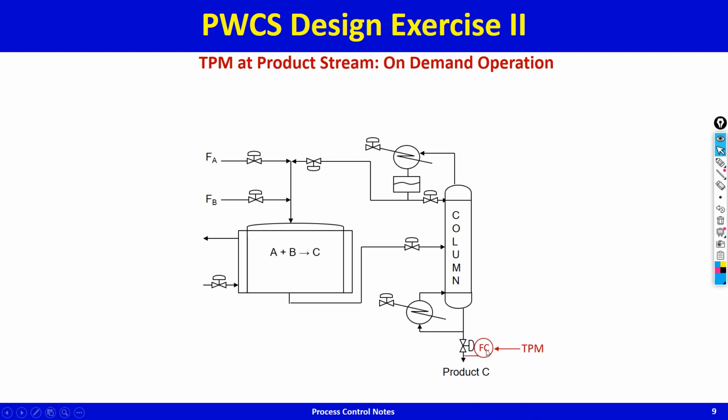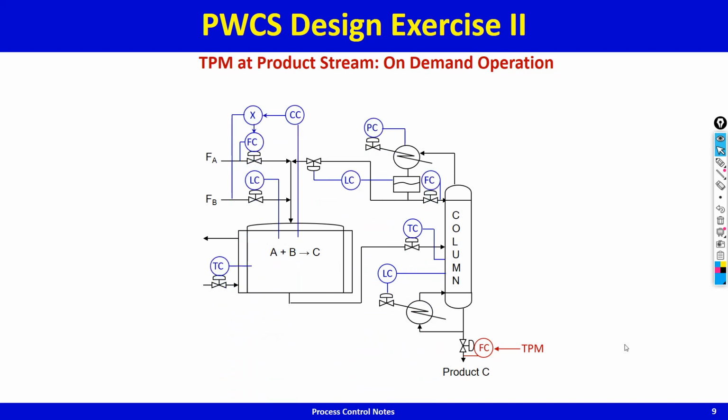and the throughput set point is being set by the user. And now that the throughput manipulator is at the product stream, level control will have to be this way, temperature control will have to be that way, level control will have to be that way, everything else is the same. Of course, optimal operation would be the same thing: level should be maximum, reactor temperature should be maximum. And then again you are left with these 2 set points that are unconstrained. How do we choose their values?